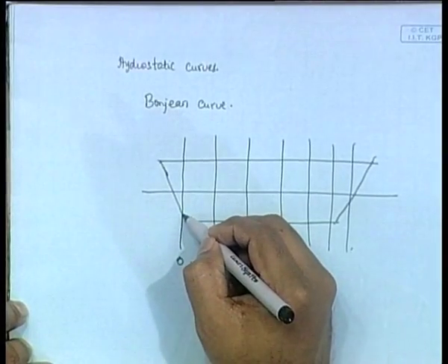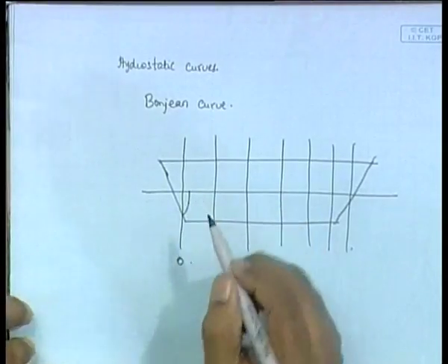Okay, you have a sectional area there, up to the water line. That is the meaning of sectional area. Your ship is here at any station, let us take station 0. At station 0, this area up to the water line, not beyond the water line, that area is usually called the sectional area.